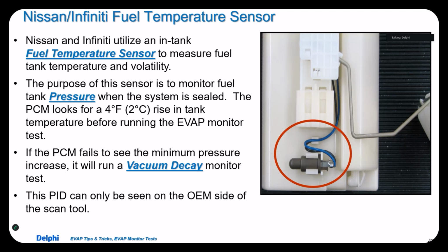If you're driving the car and you're building up pressure in the tank, if we get a 4 degree rise in the tank, that is part of the criteria for the PCM to say, run the EVAP test. Not all of it, but it's a big part of it.